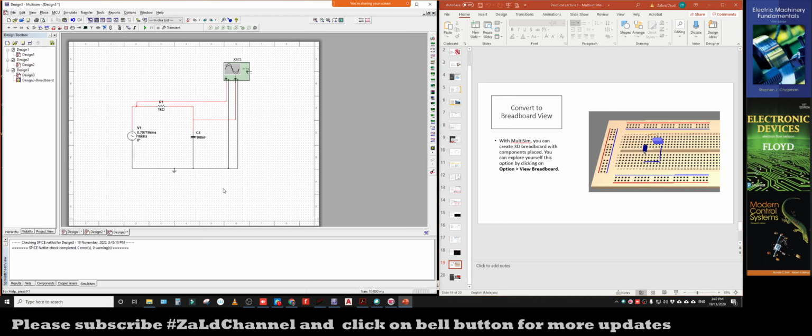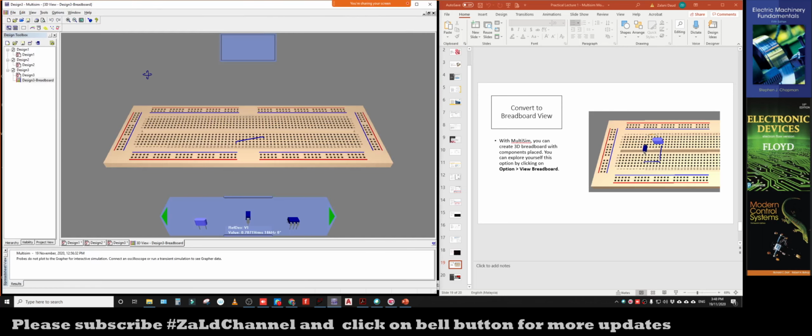So basically, finally, we have another 12 or 13 minutes. Finally, you can convert this circuit into the breadboard interface. So how to do this? Basically, we can do the transfer. You can click on view breadboard. In these tools at the top here, you can click on view breadboard, which is this one. If you click this, it will take some time to convert this into the breadboard interface like this.